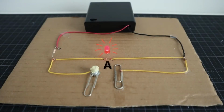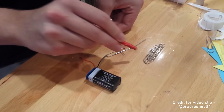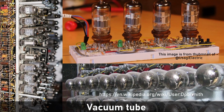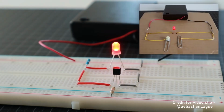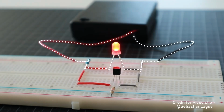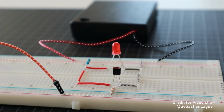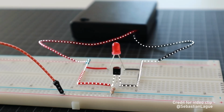I was controlling these switches by hand, which computers can't do. Originally, they used clunky electromagnets, then vacuum tubes, and finally transistors. To understand transistors, I've set up a NOT operation on this breadboard, using a transistor instead of a paperclip switch. Right now, it acts as an open switch, blocking current, but when I apply power to the middle pin, it lets current flow through, taking the easier path. So, transistors are just switches controlled by electricity instead of hands.